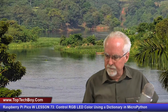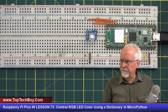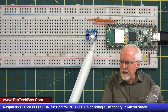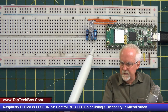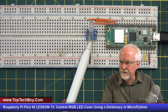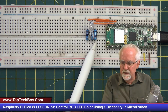Let's get over here and look at my solution to the homework assignment. I'll come over to our view of the circuit. It's really pretty straightforward. I have an RGB LED hooked up to the Raspberry Pi Pico W. The way I did it, this leg is the R leg, then next over is the long leg, which is the ground pin, and then this is the G and this is the B. So this is R, ground, G, B.